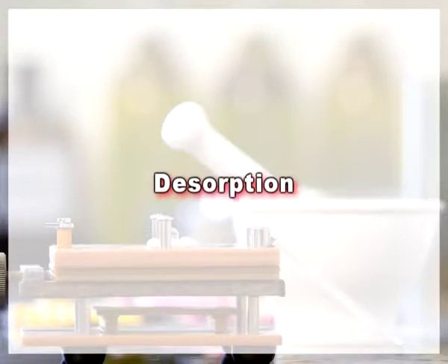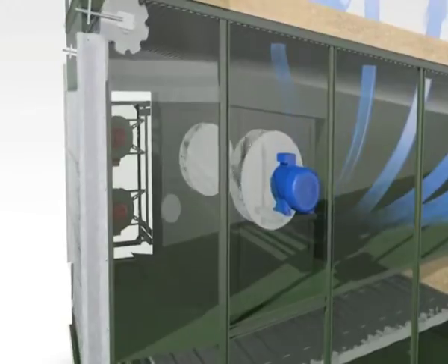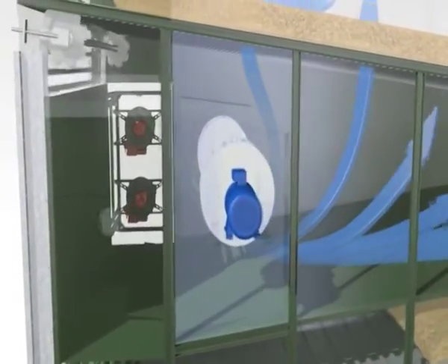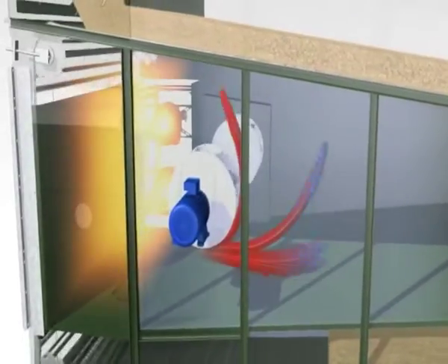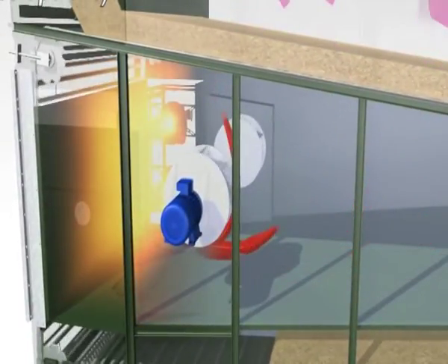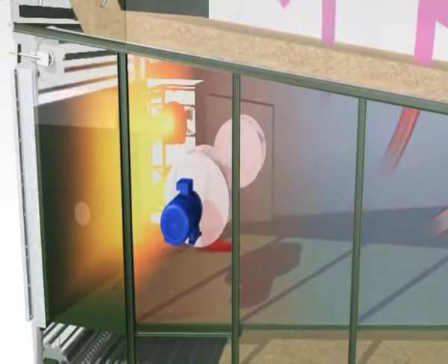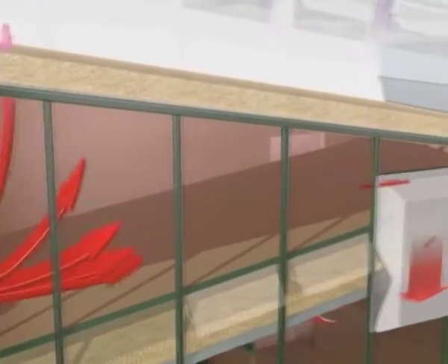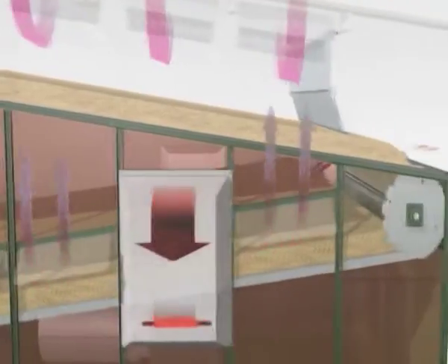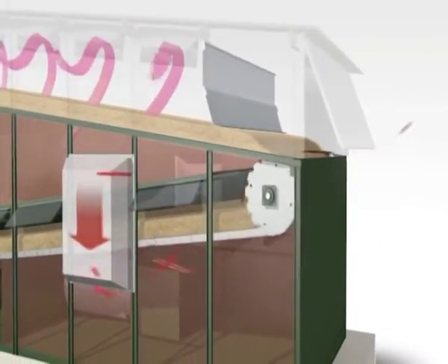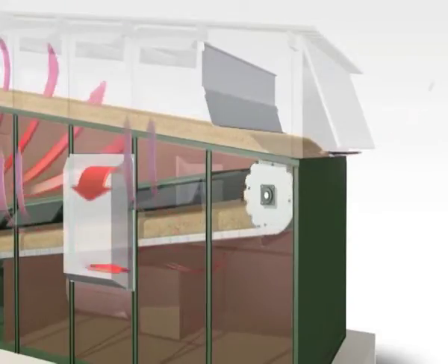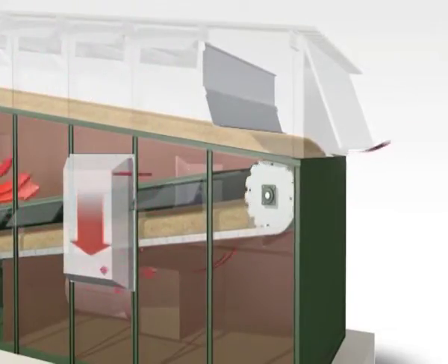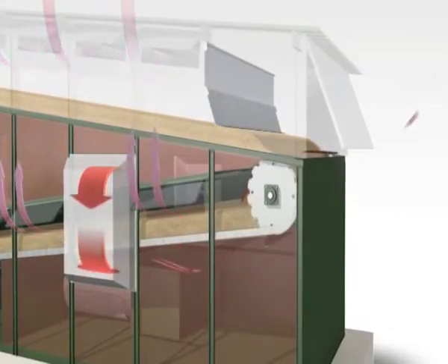What is desorption? When air is continuously passed over the solid containing moisture more than the EMC, listen, more than the EMC, then solid loses water continuously till EMC is reached. Means when the EMC is reached, drying stops. So, this phenomenon is called desorption. If excess moisture content more than EMC is present in any solid material, then material loses moisture to reach the EMC, or if less moisture content is present in the material, then material absorbs moisture from the atmosphere. So, this process is known as sorption.